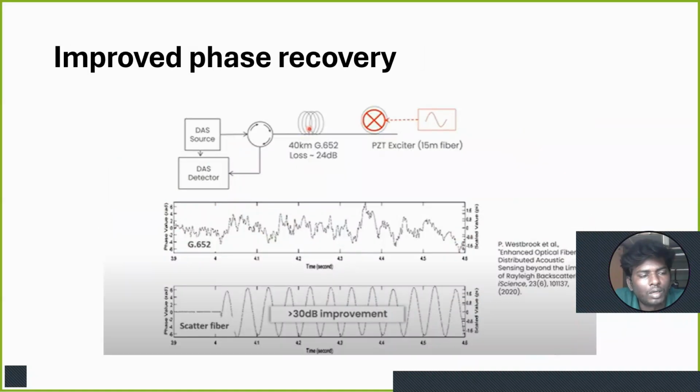Improved phase recovery. Another technical benefit is improved phase recovery. Phase data is critical in DAS applications because it gives you the frequency and location of vibration sources. Enhanced fiber makes it easier to extract phase shifts accurately, which boosts the overall performance of the sensing system.